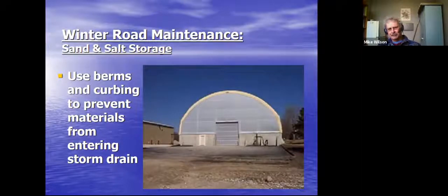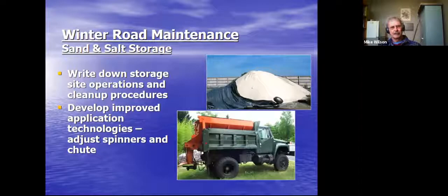So if you're storing that material in your shops, you want to use a berm and a curbing and prevent that material from entering the storm drain. You want to write down storage site operations, and clean up procedures should be put in place for those operations. You want to do this on a monthly basis or bi-monthly basis if you can.